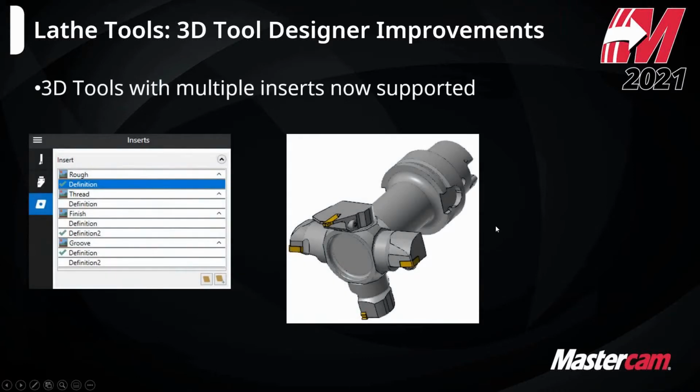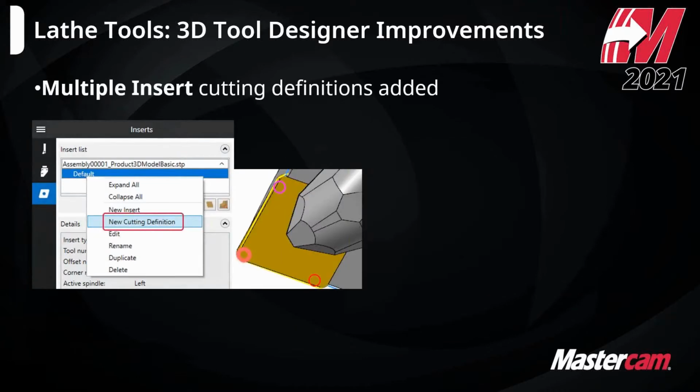So with that multiple support, we can now support multiple inserts in the same tool as well. And Alex will have a file on this, which we didn't cover in the previous general webinar, where they have these new multi-inserted tools. They're more designed around the Multis or Integrex style of machines with an upper B head, so then it can index the tool to different positions and reduce tool changes on a given job.